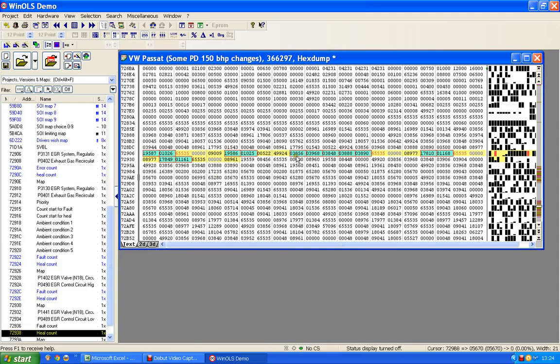And what I could now do is load this file into the car and see if I get any errors. Because obviously if I get any errors, I'll either get the MIL light come on the dash, or the MIL light won't come on, maybe, but when I do a scan for errors, I might find that I've actually got errors displayed.